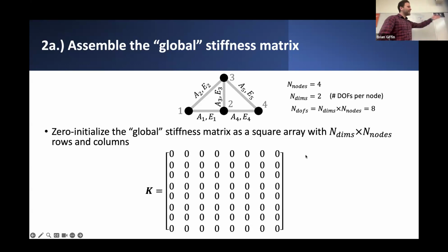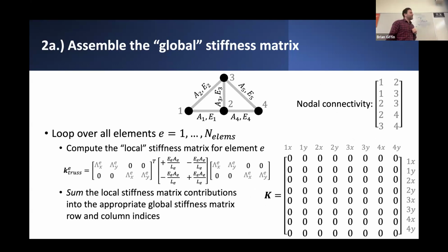So in this case, if we're setting up our system of equations for assembling a stiffness matrix, all we have to do is dimension an empty stiffness matrix that has the appropriate size to begin with. Initially we'll just set it all equal to 0 and then fill in appropriate entries through our assembly process, by looping over all the elements and then figuring out which entries of the stiffness matrix we should enter some of these summed contributions into for the global system of equations. But the procedure looks very similar to the one that you would pursue in homework assignment number 2 for these one-dimensional finite element problems.